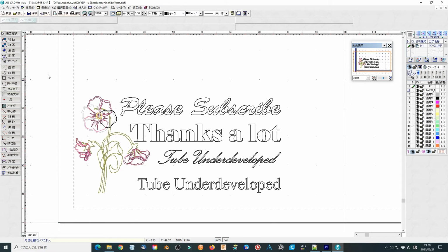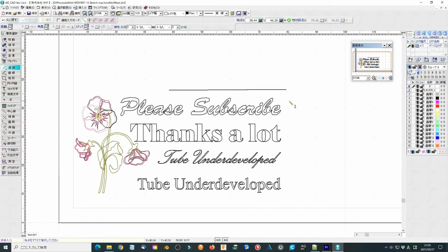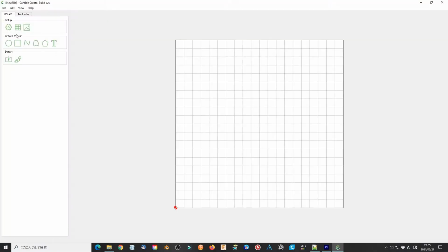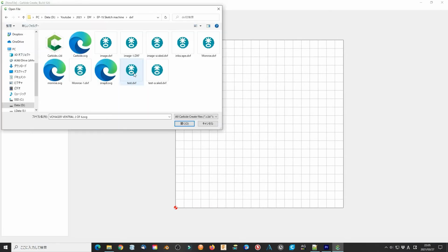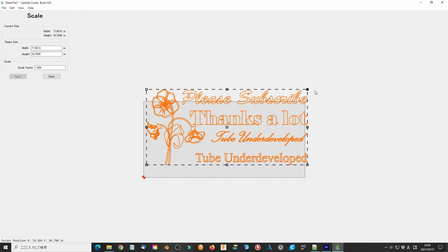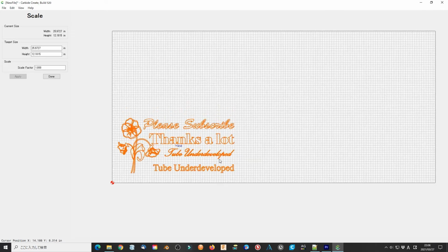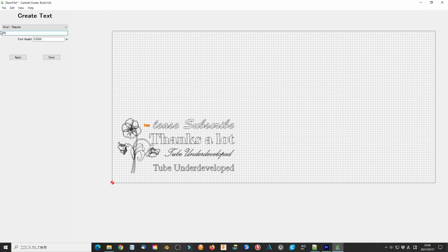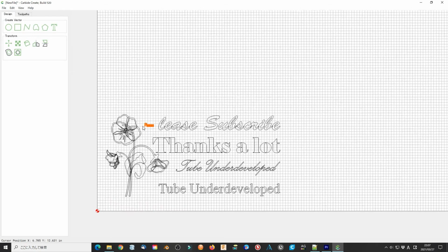It means you can adjust the DXF file in ways that DWG TrueView cannot, such as move, scale, edit, etc. Another software is Carbide Create. I strongly recommend you use this software. It is free and can modify SVG, even DXF format. The only limitation is that after that, it can only save in SVG format.